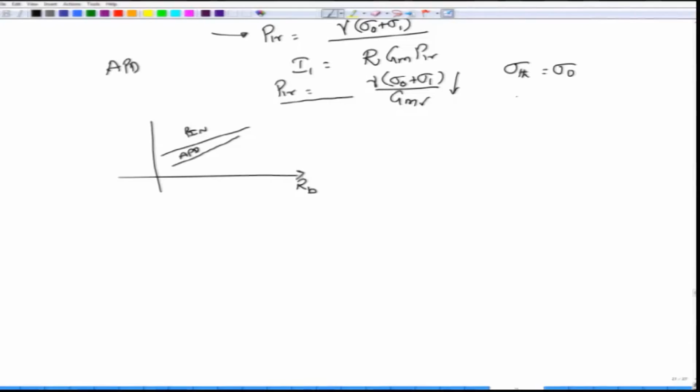However, with an APD, what would be the noise sources? Well, there is thermal noise, which you will anyway get when you have sigma 0, but when you have sigma 1, that is when you transmit bit 1, you get thermal noise as well as shot noise, but this shot noise gets multiplied by a certain factor. So, there is the GM square FA of GM, where FA is the noise factor, or the excess noise factor, of the photocurrent.